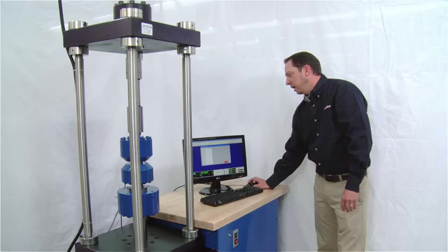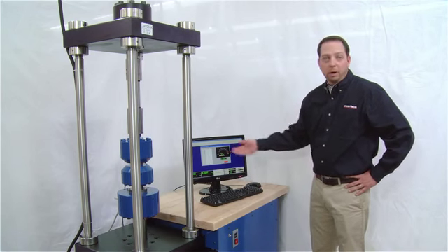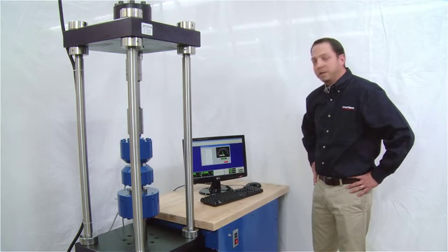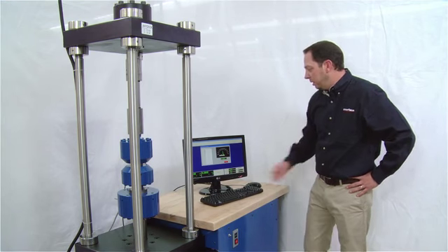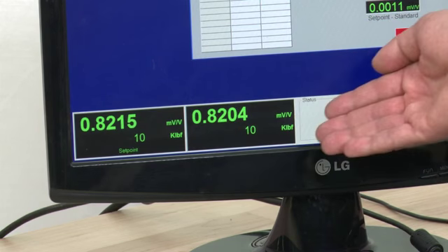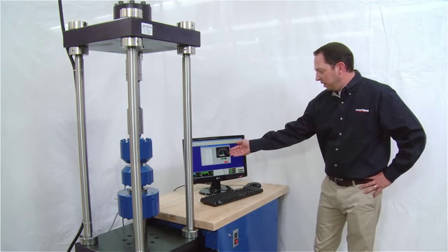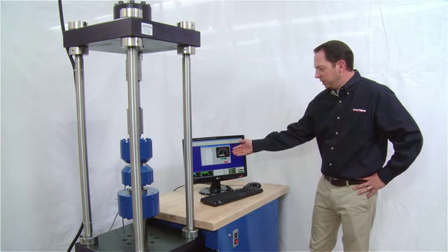So, calibration process has started. We're going to first be taking our 0 point, which it already did. Now it's going to be proceeding on to the 5K value. The window here on our left is our desired set point value. This is the output from the standard currently. As they start to get close, the analog meter up here will show you the difference between the two.